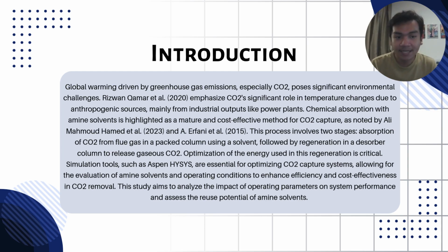A power plant flue gas, which usually has emissions of 300 to 700 grams of CO2 per kilowatt-hour, enters the bottom of a packed column, flows upwards, and encounters a CO2-absorbing solvent that is circulated countercurrently. Simulation tools, particularly Aspen HYSYS, play a crucial role in optimizing CO2 capture systems before industrial implementation. These simulations enable researchers to evaluate different amine solvents, optimize operating conditions, and determine the most effective configuration for